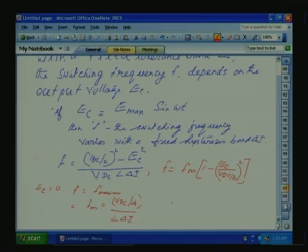So, let us write down. For sine triangle PWM, the maximum value of the sinusoid E maximum varies depending on the modulation index. The modulation index for sine triangle PWM, as we said, for a half bridge converter can go from 0 to 1. So, let us write EC is equal to M VDC by 2 into sin omega t.